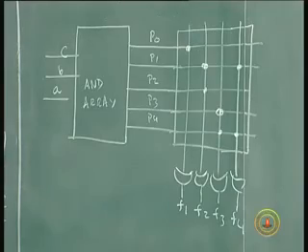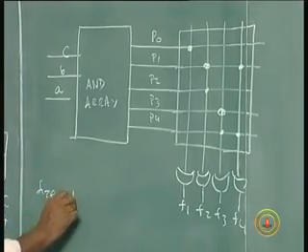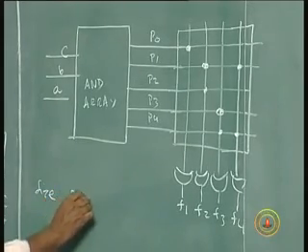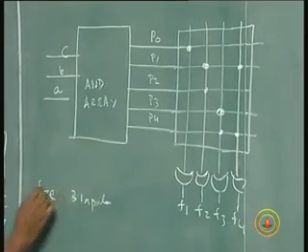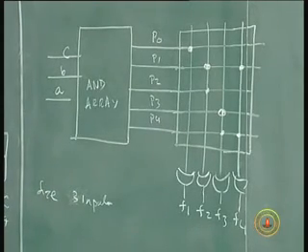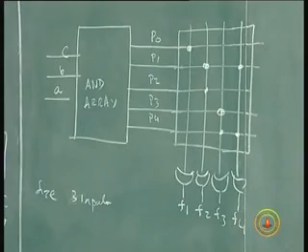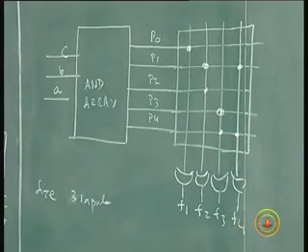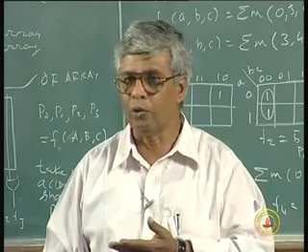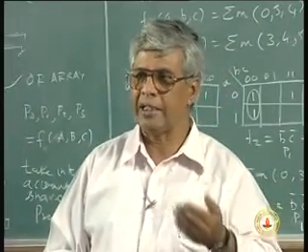The size of this would be, here you have to say, 4 product terms. I should have the capacity to have 3 inputs. So how do you express the capacity here? For the ROM, you express the capacity as 2 power n times m, where n is the number of inputs and m is the number of outputs. If you want to do a ROM based design, you cannot go to the shop and ask for 2 power 3 times 4, which is 8 times 4, 32.